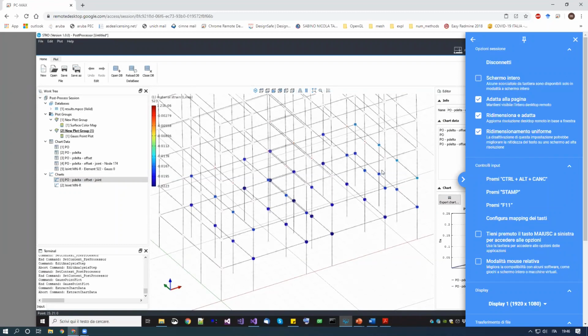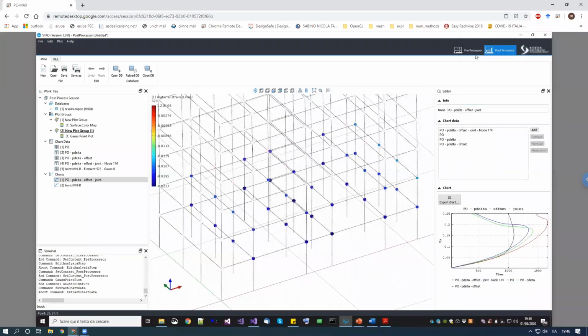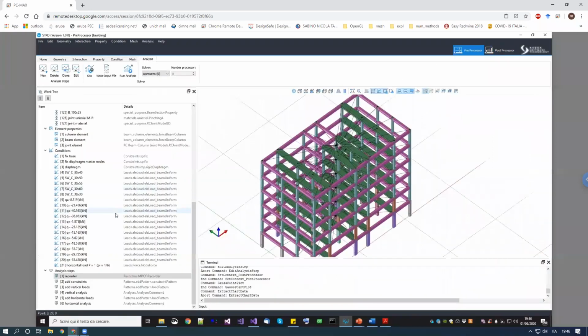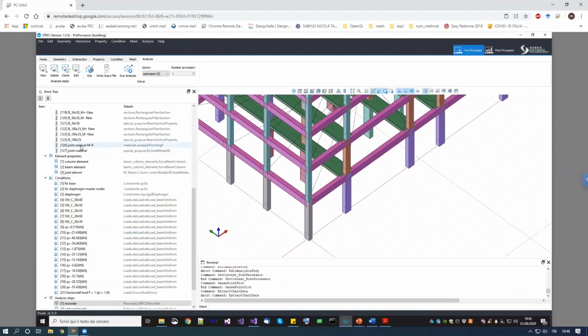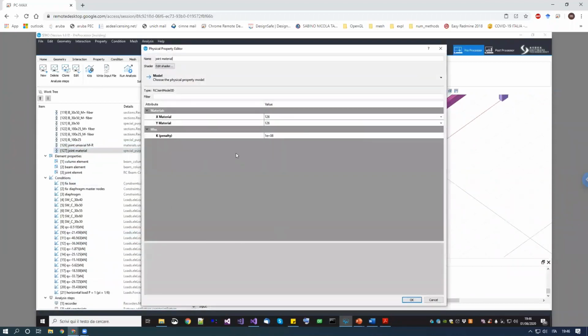Okay, so next question. How to ensure the rigidity of the joint structural detailings. Well, as I told you, let me go in the previous processor. The rigidity of the other degrees of freedom that are not involved in the nonlinear modeling of the joint, so the other 6 degrees of freedom, as you can see here in the joint material, can be ensured using this penalty parameter. As I told you, this depends on the properties of the converging elements and beams.